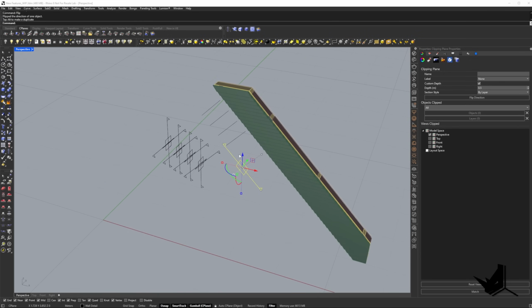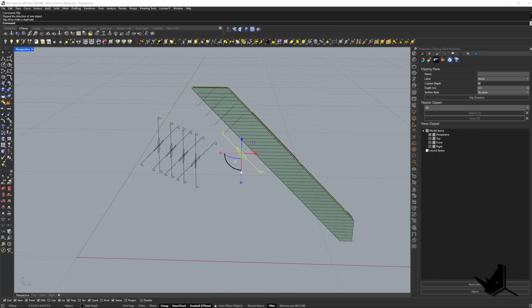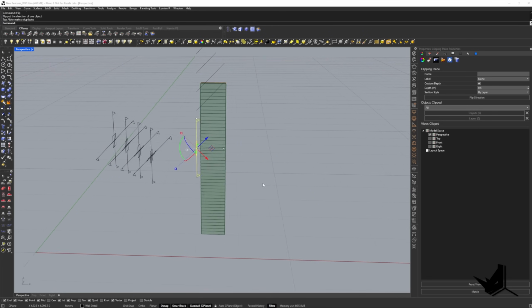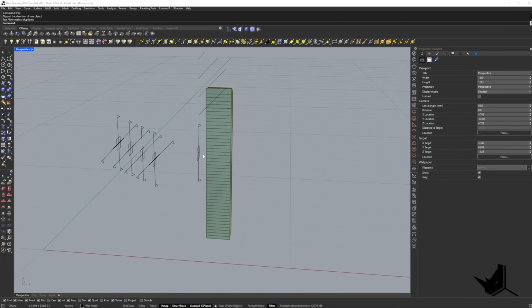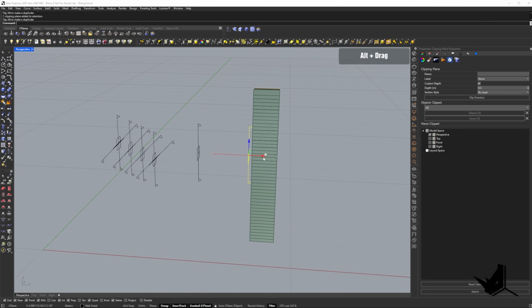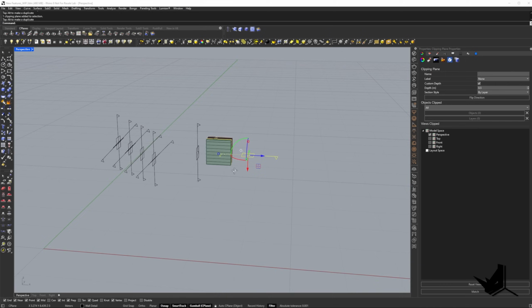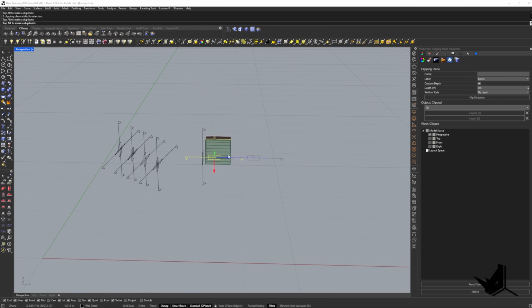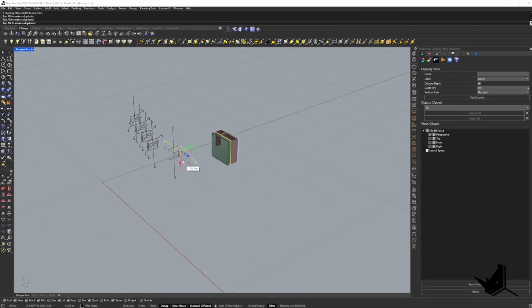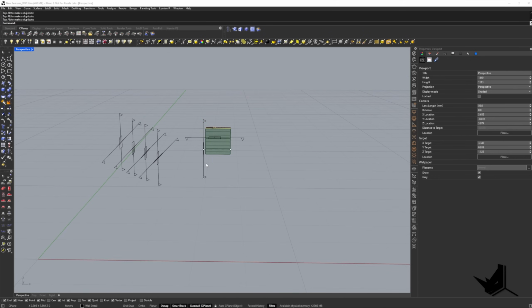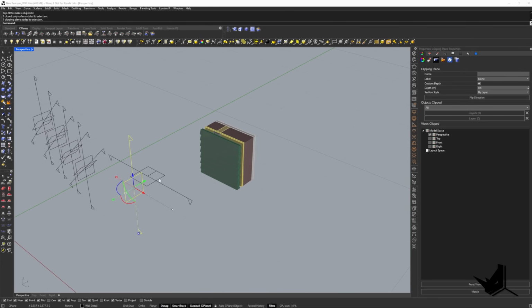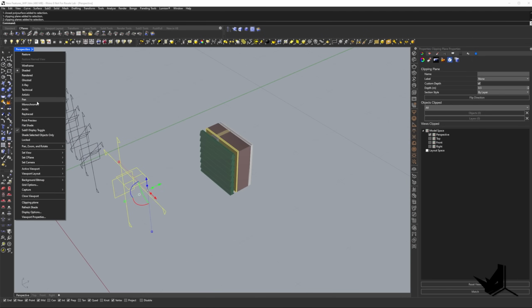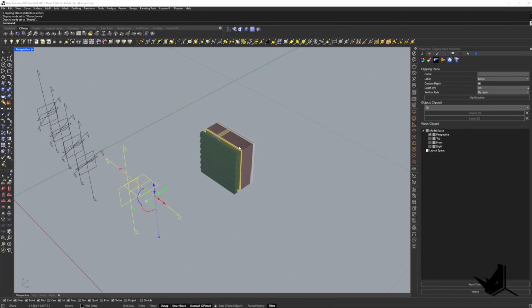And you can have like boxes of different planes that are going to be cutting through your object. For example, you can rotate this to, let's say, 45 as it was before. And then what you can do, you can select this one, you can copy it, and now I'm gonna flip it. I'm gonna do 90, and you will see here, just like this, we have the ability to create just this detail. Okay, you can see when I go up and down what's gonna change, and just like that. So this is like controlled by the depth, and if you have these 2 turned on, that would give us this particular detail that we can later on play with and export in the layouts.